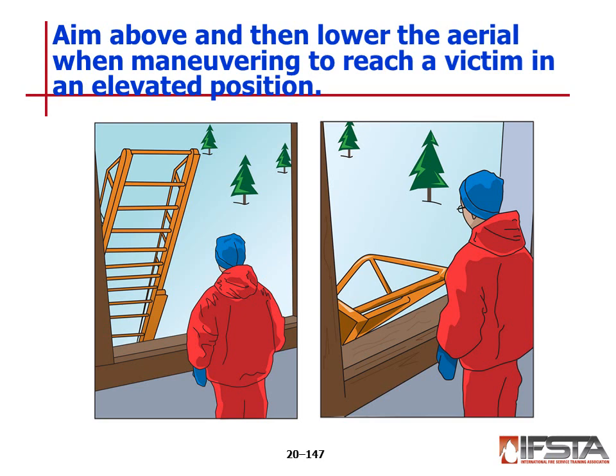When maneuvering an aerial device to reach a victim trapped in an elevated position, the aerial device initially should be aimed above the victim and then lowered. If the aerial device is raised from beneath, a panicked victim may jump for the tip of the ladder or platform on approach. The victim's action could injure the victim, or a firefighter could potentially damage the aerial device. The rescue firefighter should be prepared to climb the ladder. Instruct victims on how and when to board the device. Instructions may be in the form of hand signals, audible instructions, or both.